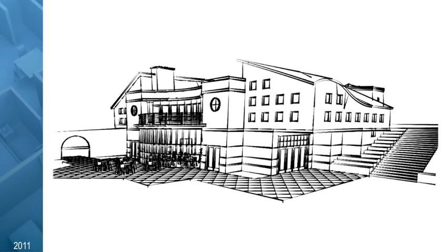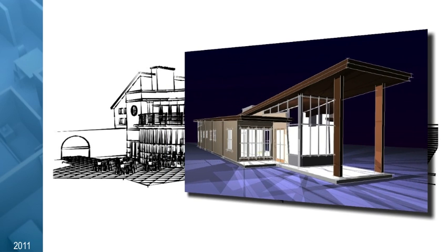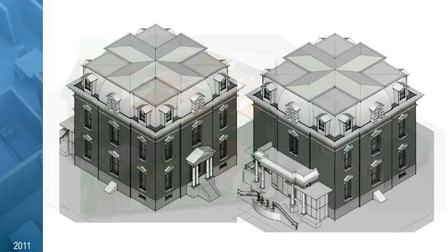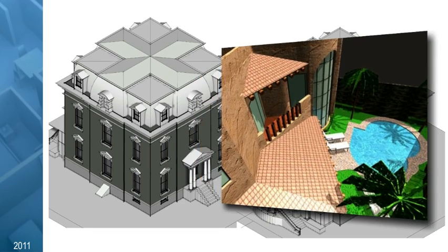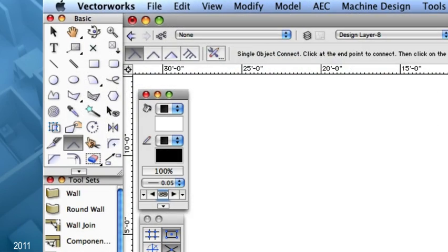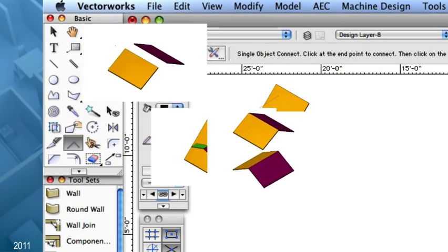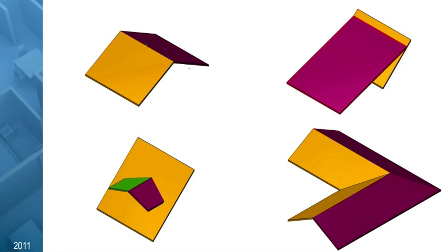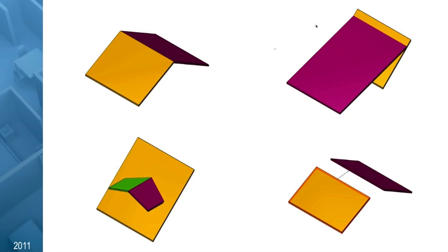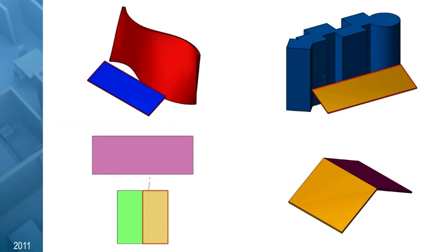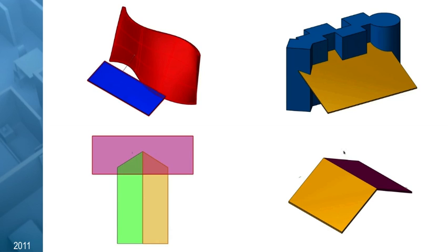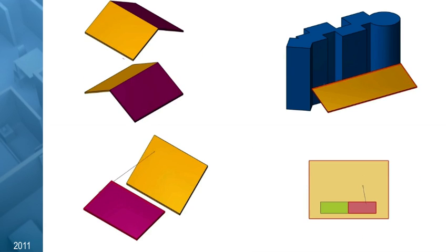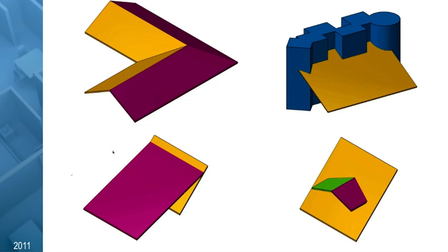So now that we have spaces, walls, and slabs, what's next? Roofs, of course. Arguably one of the more tedious tasks sometimes, we've made exploring roof design options a snap. By extending the functionality of the Connect Combine tool, you can now have the ability to automatically connect roof faces to a variety of objects. And since the tool has several modes, you can choose from a variety of trimming and joining options. You say you need that dormer roof to automatically resolve onto the main roof? 2 mouse clicks and you're done. This tool will definitely become your friend.